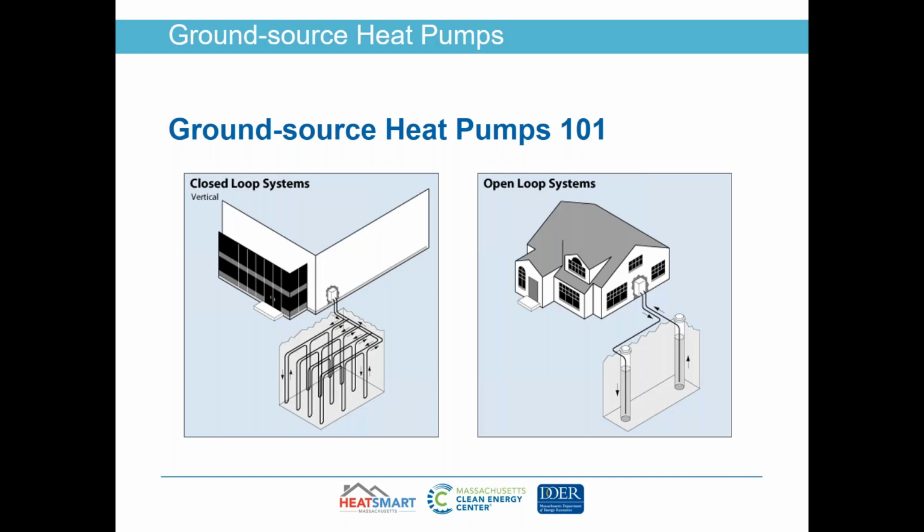And then a plastic pipe will be installed in that borehole. The heat pump will pump heat through the pipes down several hundred feet into the ground through the supply pipe, and then return through the return pipe. Essentially it will pick up heat from the ground as the water antifreeze mixture is pumped through those pipes. This is an extremely efficient process because the ground tends to remain at around 50 degrees year round.